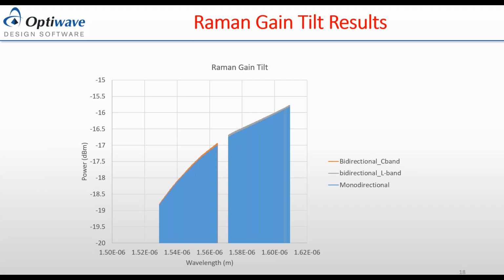Another question is whether the CWDM, DWDM signal wavelength should be within 110 nanometers of a 980 nanometer Raman pump. Now, 980 nanometers is far away from the signals, which are in the C band or L band. Typically in C band and L band amplification, we use 14XX nanometer pumps, like 1450. If you have 1450 nanometers, you typically amplify signals around 1555 to 1560.